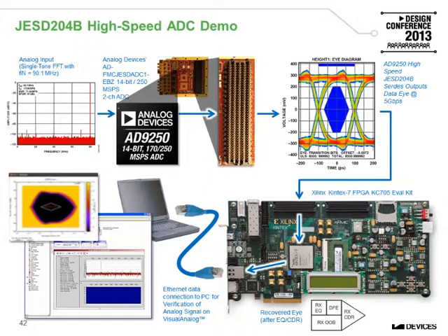In addition, we visualize the data also on a Linux graphical desktop system that runs on the Zynq FPGA ARM Cortex-A9 processing system, while concurrently solving the most challenging hardware design verification task by measuring and visualizing the receiver eye margin on all JESD204B lanes.